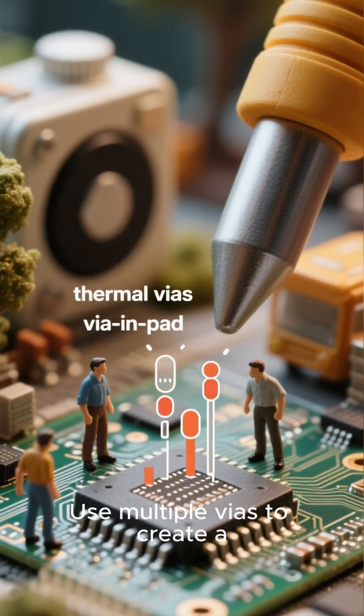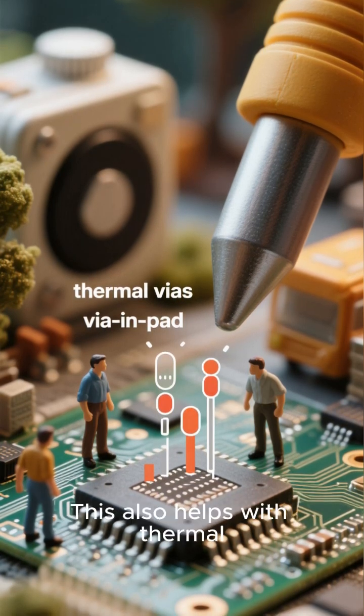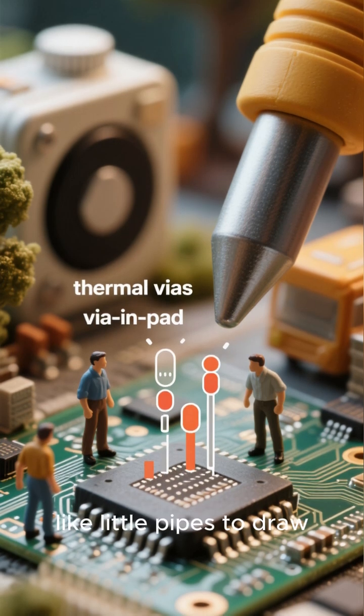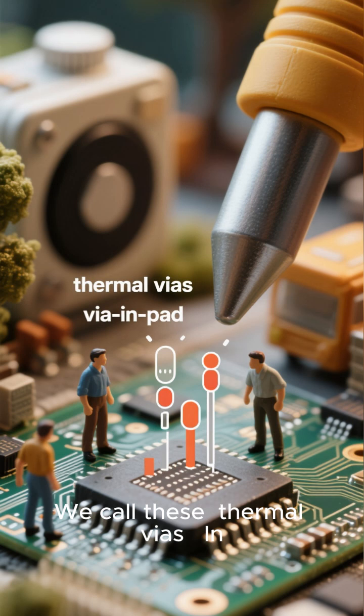Use multiple vias to create a low-resistance connection between your planes. This also helps with thermal management, as vias can act like little pipes to draw heat away from components. We call these thermal vias.